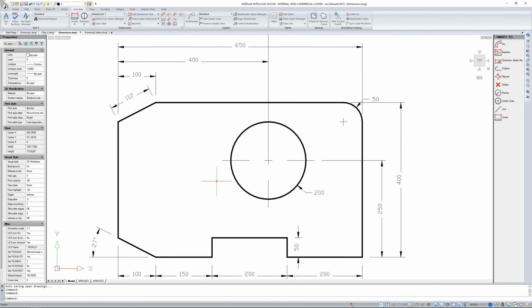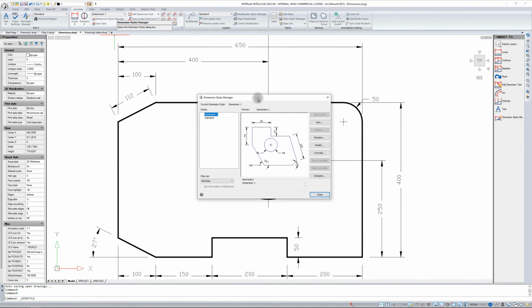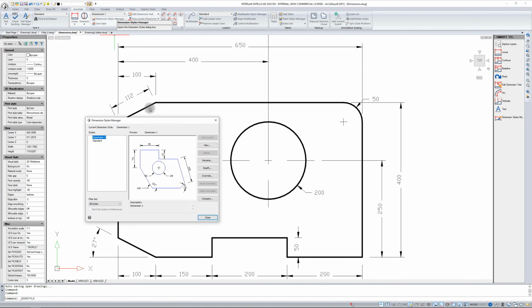But I'll also be moving on to another project where I can discuss the elements that I'm introducing, these different types of dimensioning. So you enter the Dimension Style Manager on the Annotate ribbon. In this part of dimensioning, here, you can add your own dimension style. Why are we doing this? When you have different scales used in drawings, generally the drawing will be on a 1:1 scale, but sometimes you want to detail something. So you draw details that are enlarged in relation to our model. They are 2 times bigger, 4 times bigger, or 5 times bigger.